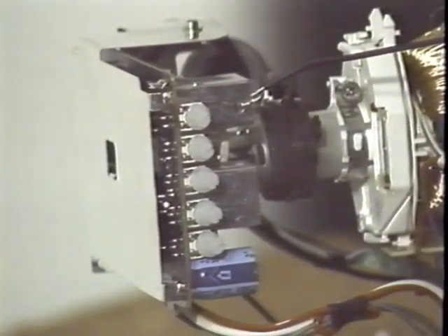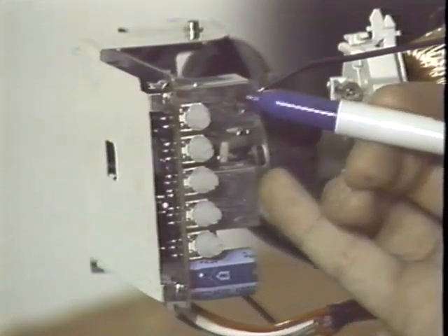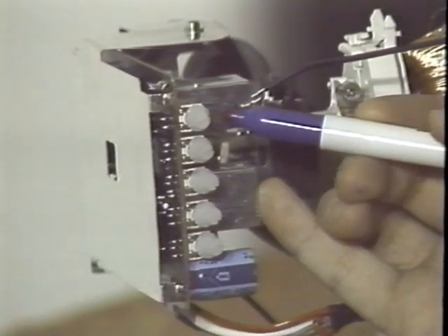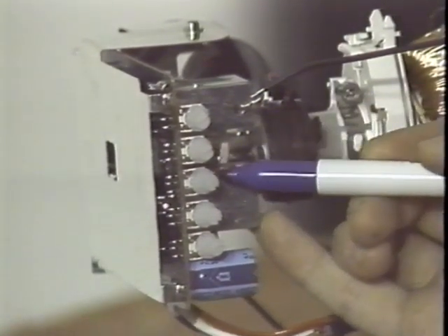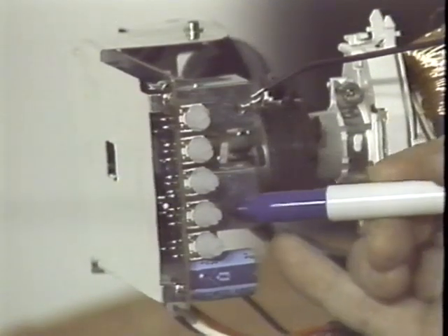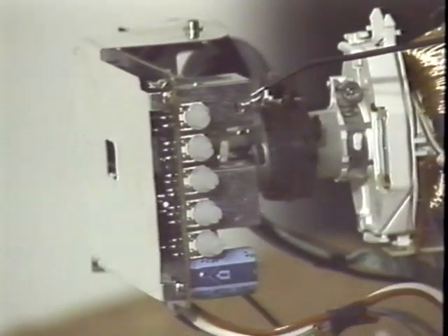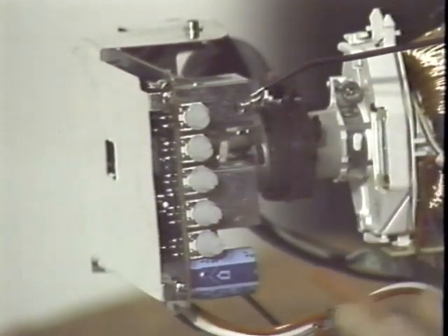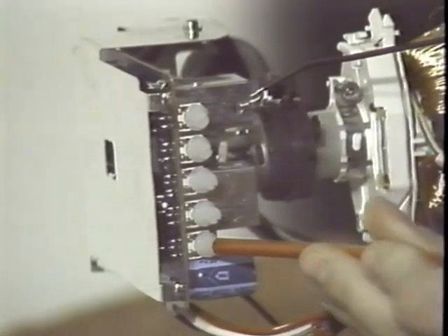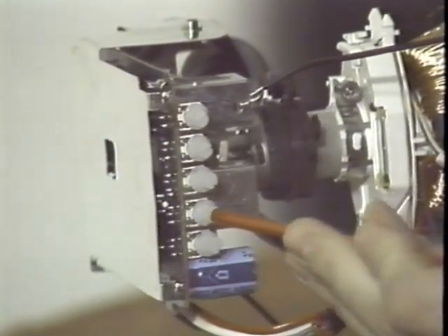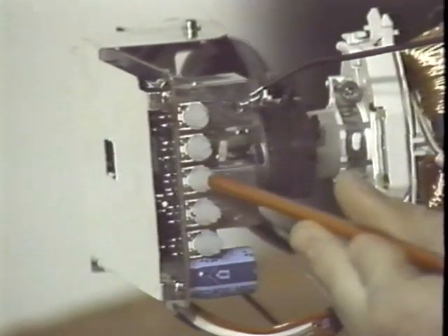The first one is called the purity adjustment. Here you use magnets to align the electron beams so that each beam strikes only one color of phosphor. You will need a full red screen and later green and blue screens for this adjustment. One way to obtain these displays is to override the blanking circuitry of the monitor and turn the bias of the appropriate electron gun all the way up while turning the other two down. This results in one gun remaining on at all times, which produces a full, solid color screen.